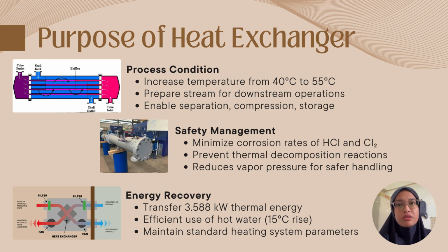The second one is safety management. Controlled heating helps minimize corrosion caused by HCl and chlorine, prevents thermal decomposition reactions, and reduces vapor pressure for safer handling. Lastly is energy recovery. The system transfers 3.588 kilowatts of thermal energy using hot water with only a 20 degrees Celsius temperature drop, ensuring efficient energy use while maintaining standard heating system parameters.